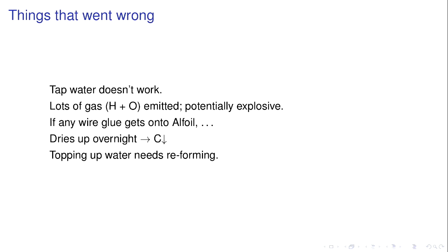If you leave it overnight, it dries up a little bit, especially in these hot weathers, and so your capacitance decreases. When you top it up again with more demineralized water, you need to reform that bit of the capacitor that you've just put in there. Theoretically, you wouldn't need to do that.